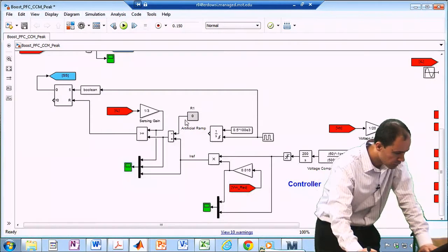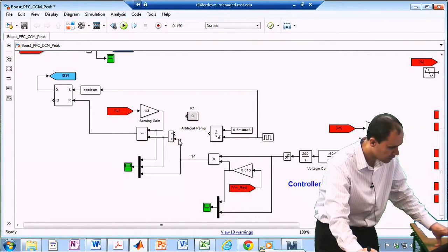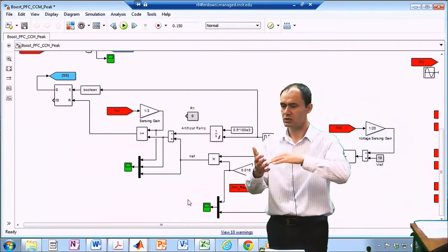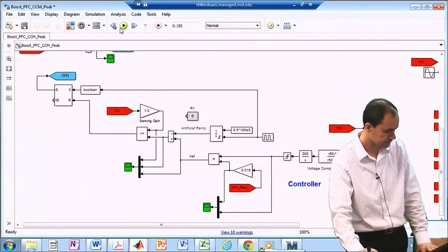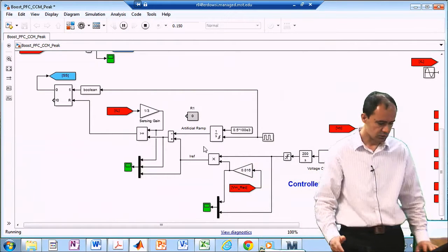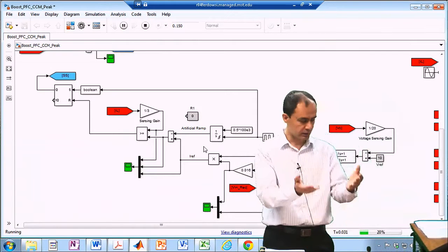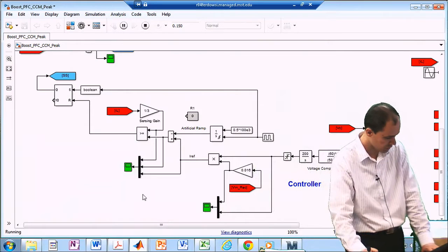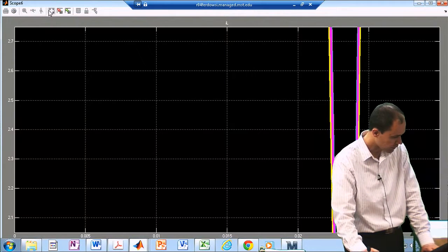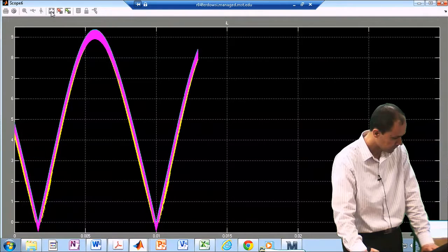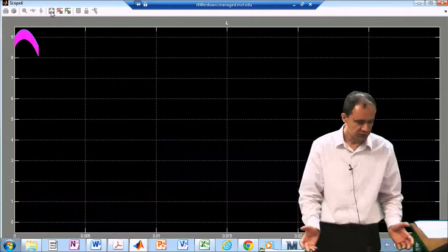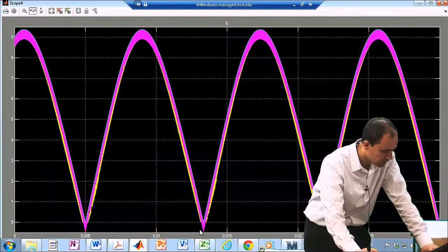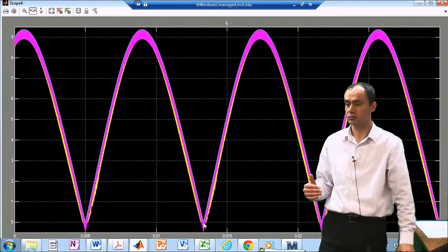So there are papers trying to solve this problem. One of them is to add a little bit of a DC bias to the overall signal. So you're actually raising it so that the reference for the inductor current, from which the external ramp is subtracted, touches 0. It doesn't go to negative territory. There are papers suggesting to shift everything just a little bit up, like a couple of volts or something, so that this negative area in the bottom gets adjusted to 0, something like that.